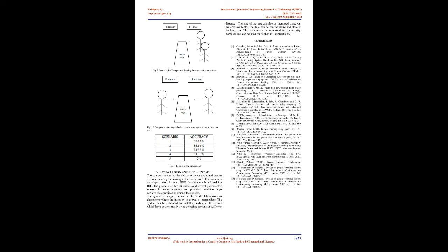The person passes through both the IR sensors, but since there is a delay in activating the piezoelectric sensor, only one of the sensors gets time to detect by the time a person passes through the system and the count is detected. The system is designed so that even if two persons enter or exit simultaneously, the threshold is set to detect the two persons and the count is increased by 2.